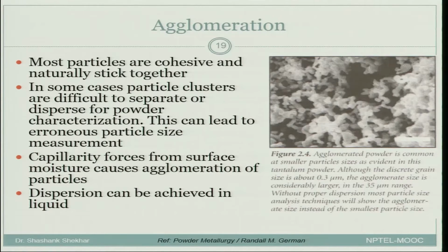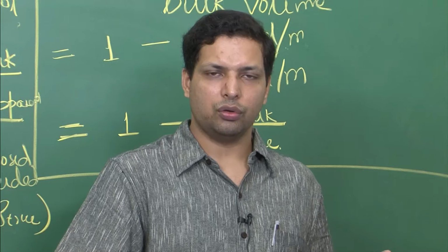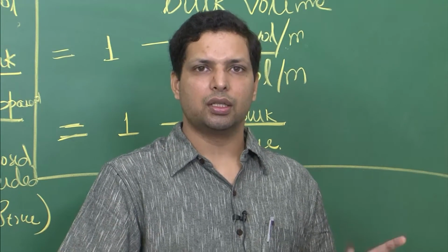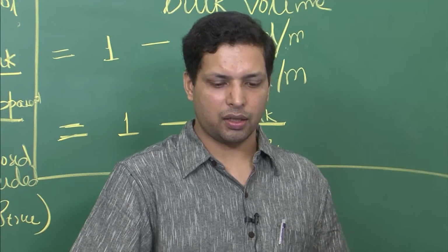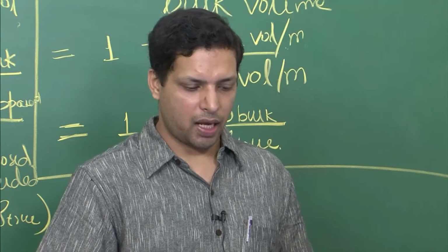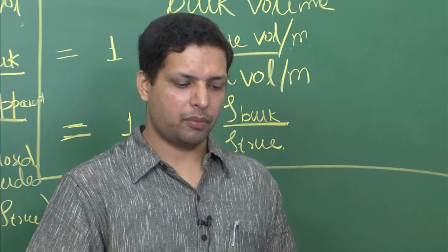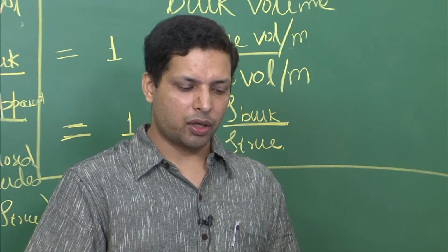Now in the liquid, the surface energy term changes, and because of that you can get dispersion, and therefore you will be able to have particles of their natural size, and then you can do the characterization. That is why you remember in most of the techniques that I showed you, the particles were actually in some solution. When they are in those solutions, they do not stick to each other and they remain separated, and then you can calculate the actual particle size. So at this point we are coming to the end of the characterization of the powder particles.